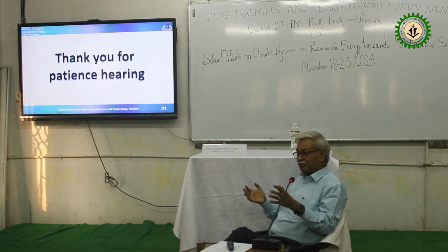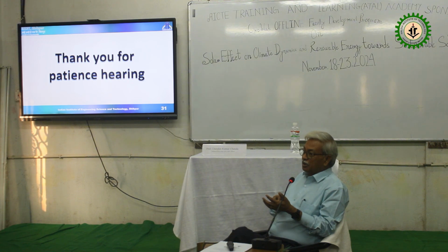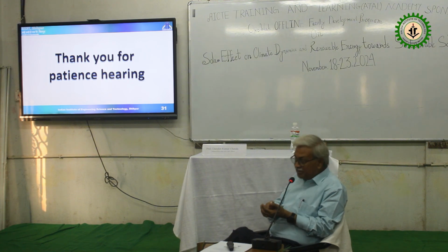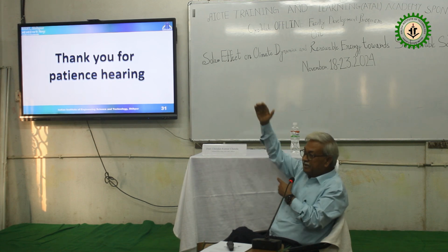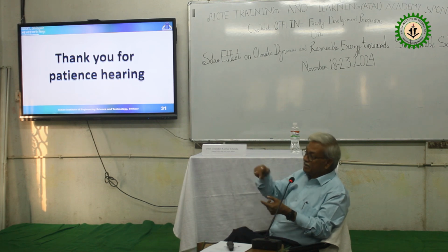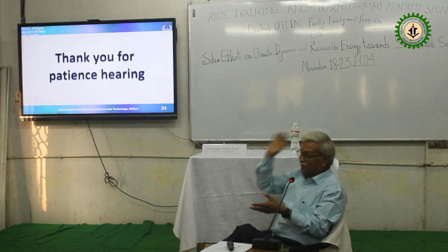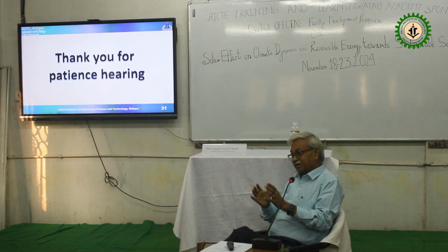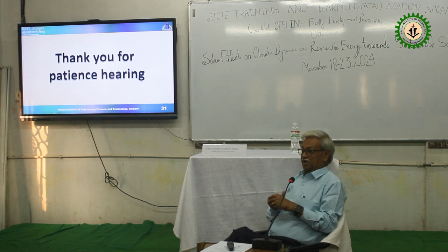Why pump storage? Pump storage means during lean hour, we are using the electricity, burning the coal and pumping the water to the head. It will create a head. When there is a huge demand, again we will generate. So we are getting electricity by burning coal and by electricity only. So I was dead against. But when the renewable energy penetration came, then I thought that this is required.